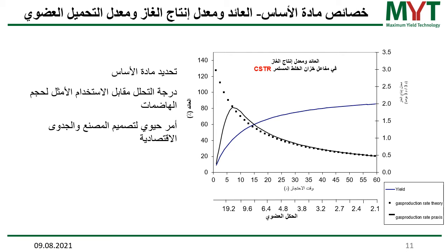So usually for a CSTR system, you would think of at least 5 to 6 days of retention time, which would already require a very easily degradable substrate with a high content of already dissolved substrates in order to make life for microorganisms as easy as possible.